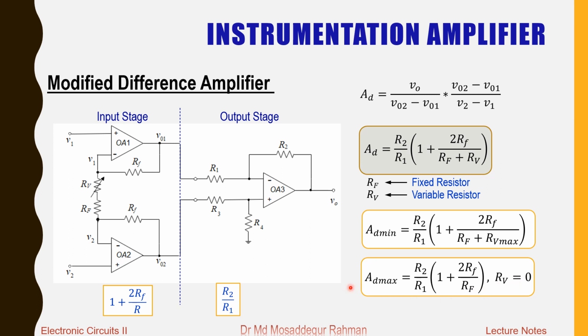So this modified circuit is known as the instrumentation amplifier, that is widely popular in the industry. Because of this popularity and because of all these desirable features that we look for in a good amplifier, this circuit is constructed as one single IC chip like op-amp.